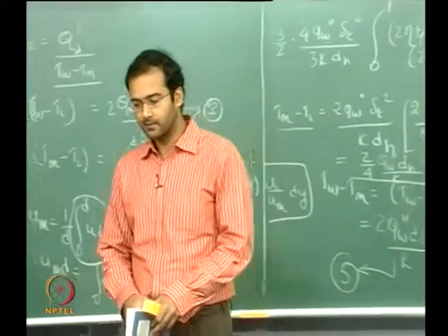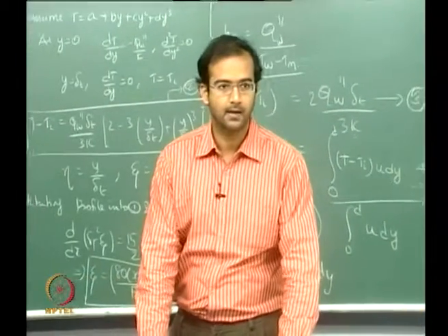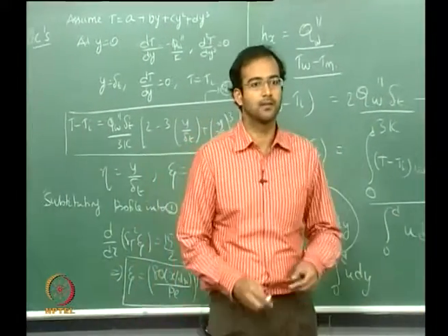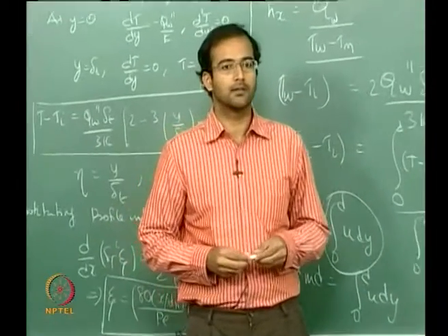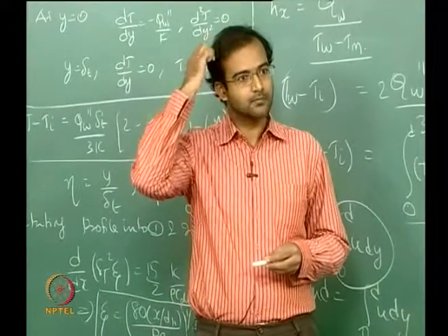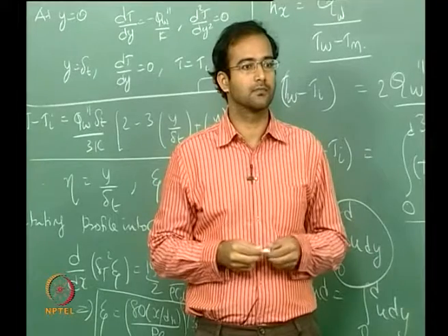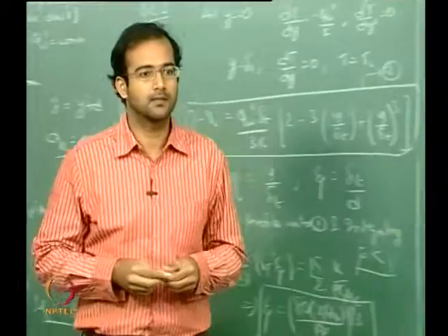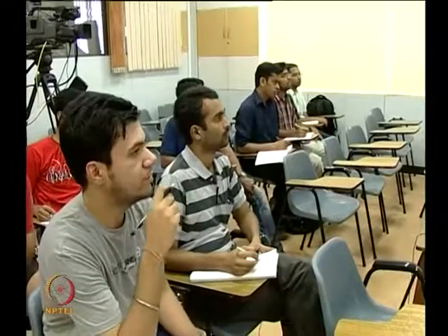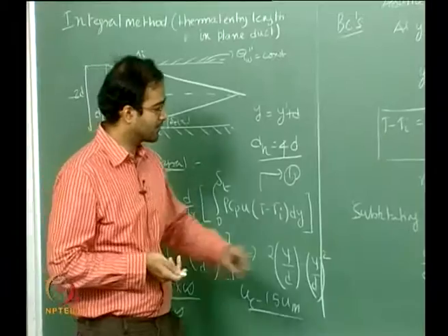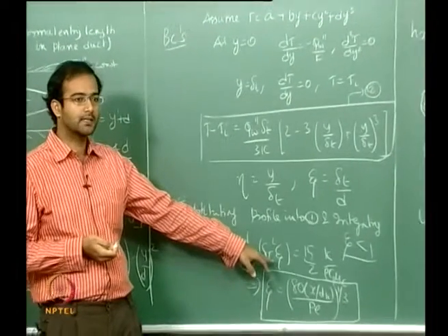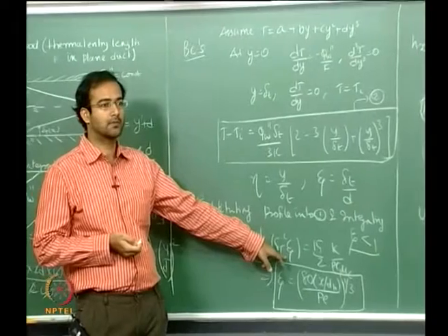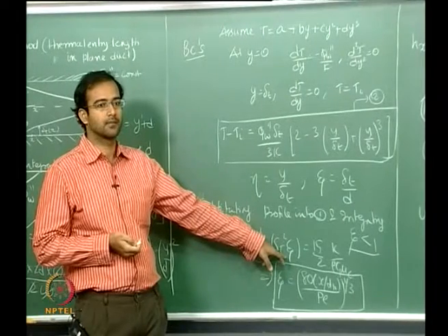This is because the integral method is not valid for the asymptotic limit. Why? The boundary layer is merged, so the boundary layer approximation is not valid anymore. And the other thing, in the energy integral we have neglected the higher order terms of zeta, correct?